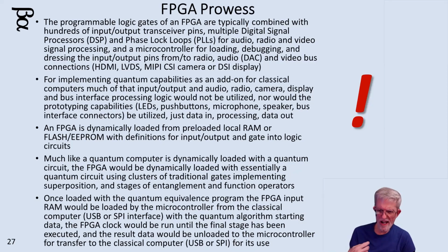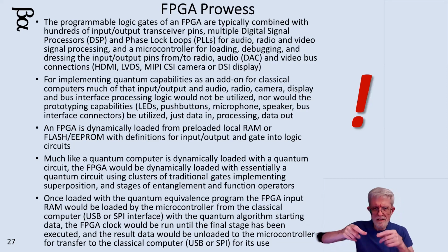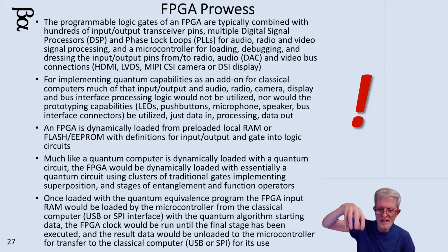So you can take in audio and produce audio out. So you can have something that sweetens your audio, or you can have something that produces test patterns of video data. They're now sophisticated enough that if you wanted to make a little tiny game computer that had a display, you could actually make all the controller inputs and the display outputs with a single FPGA and its microcontroller. The instructions that go in the FPGA, those can be loaded from local memory, or they can be stored in flash memory associated with the FPGA itself or off board from it.